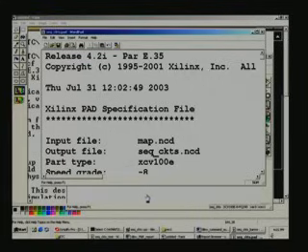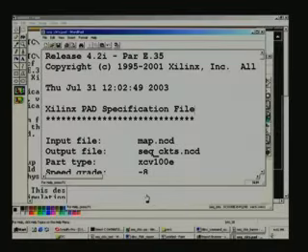You have a question? You said the level is TTL compatible, isn't it? Yes. Can we have other compatible levels also? MOS, in fact these FPGAs are basically MOS base version. So they have what are called TTL tolerant voltages. The chip itself may be working at 1.5 volts or 3.3 volts and so on. So no matter what the supply voltage is, they will have compatible IO, so that any other TTL or any other device, CMOS or MOS, can be connected.